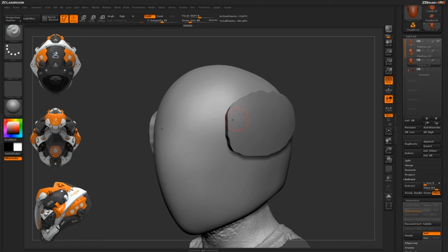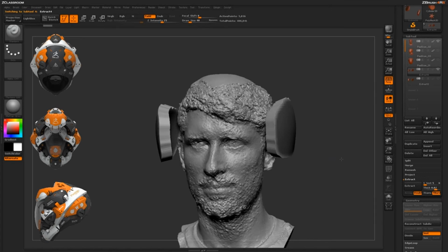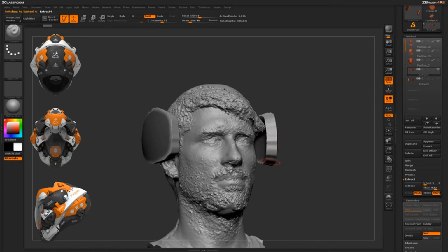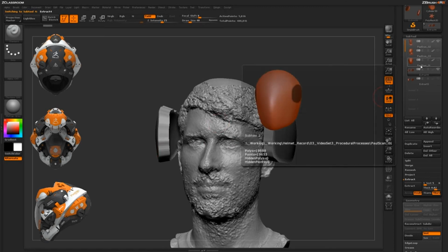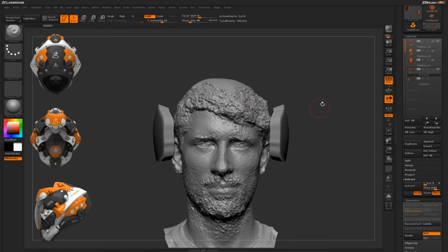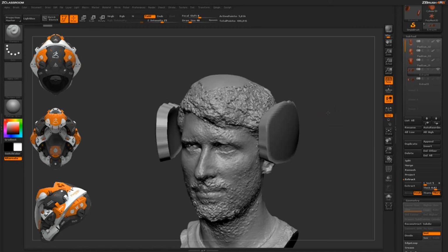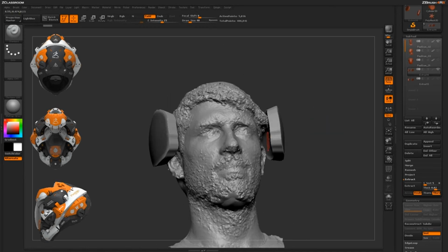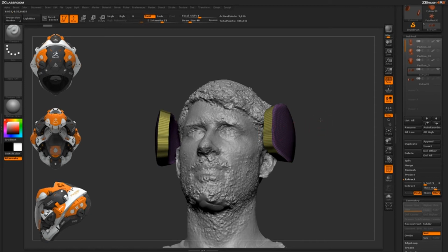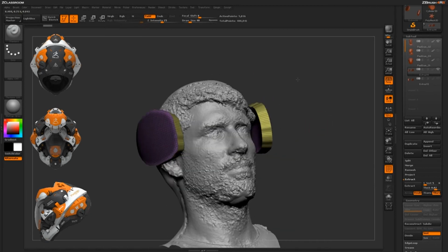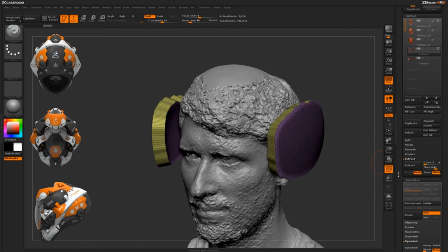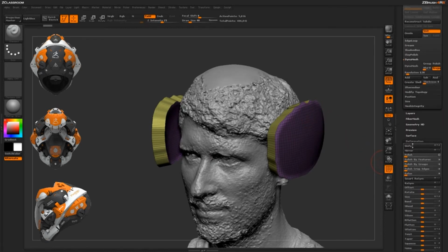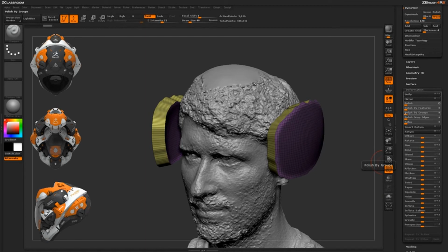structure. So after you're happy with the thickness, come over here and hit accept, and now it's going to generate a new subtool for it. And so as you can see, this one that it generated now has given me that clearance that I've already established from that initial base mesh that I pushed out away from Paul's scan data. So now that you have this flushed out, you'll notice you get some nice poly grouping around this area here. This poly grouping comes into play because you can actually polish based on this grouping. So if I come down here to the deformation panel, there is a polish by groups feature.